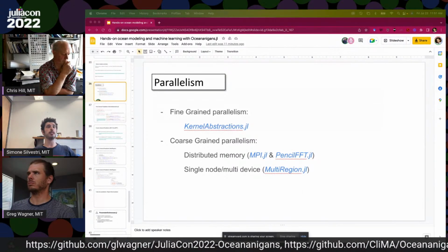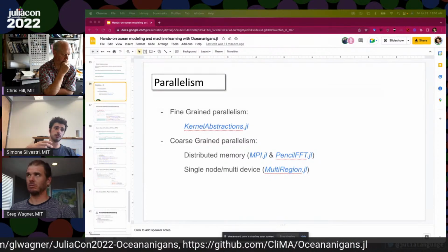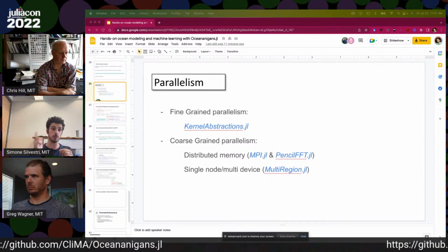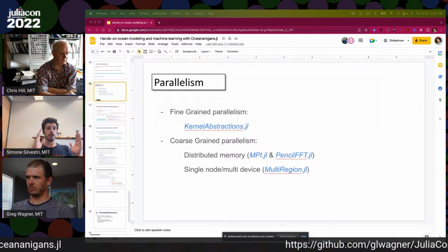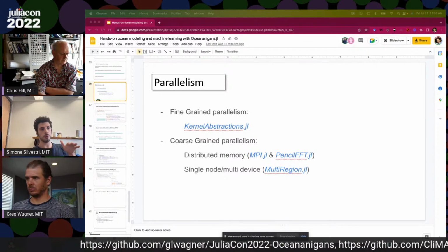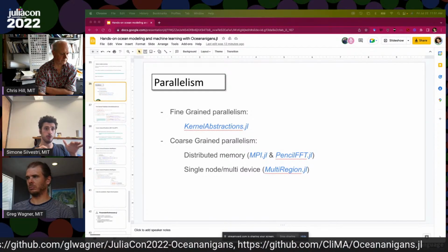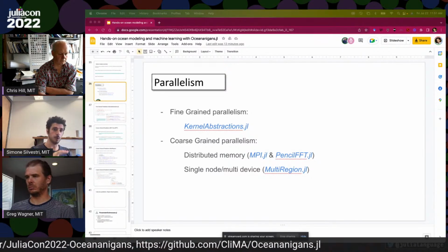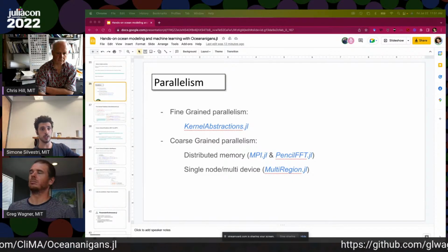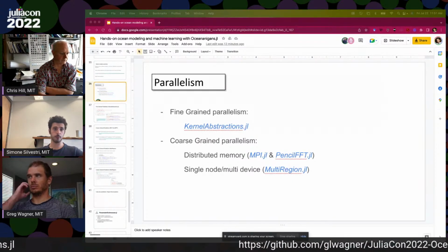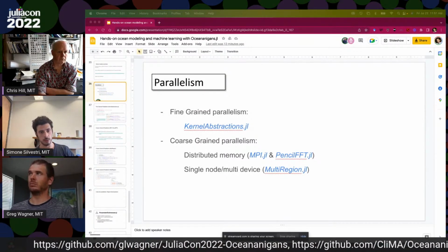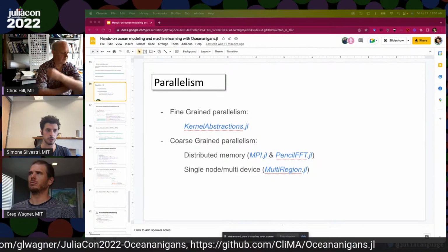So you can imagine that we discretize our whole grid in pencils or slabs, across either the X or the Y or the X and Y direction. The PencilFFTs routine will transpose our data in such a way that one direction at a time will be local, perform the FFT, and then transpose in the other directions and perform the FFT, such that we have all our data transformed in the wavelength domain. Then we can perform our derivative and come back to the spatial domain. And this is all implemented through PencilFFTs.